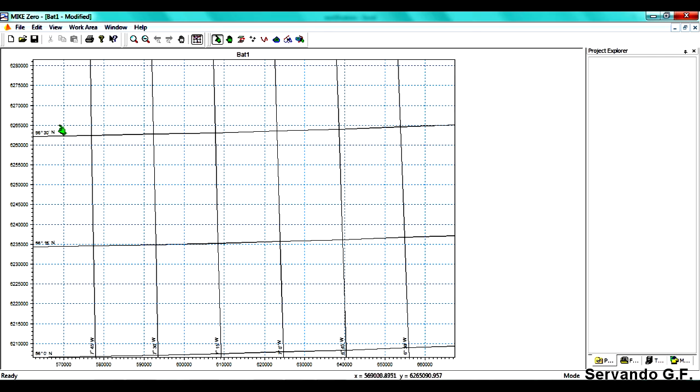So okay, as you can see here, what MIKE shows us is two different grids. One is this blue dashed line perpendicular to those edges, and then there is this black grid. This black grid is the map projection WGS 84 for zone 29. So of course, as it's trying to adjust a plane to a sphere, which will be the Earth. Well, it's not a sphere, but let's keep it simple. It's not perpendicular to the edges of the screen.